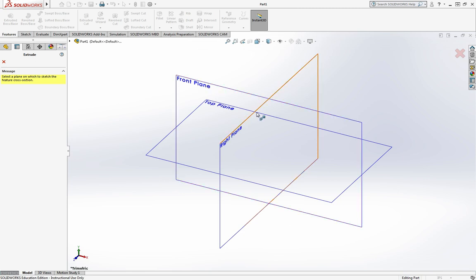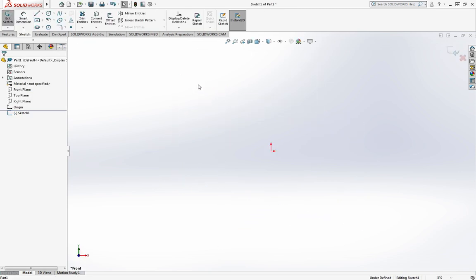Then you can click which plane you want, and then it will take you normal to, or straight on, that plane. If you select sketch, then you have to select the plane, but then you have to move there manually, normal to yourself. SolidWorks doesn't automatically make you face that plane straight on. You look at it crooked until you change your view up here to be whatever plane you started working on.